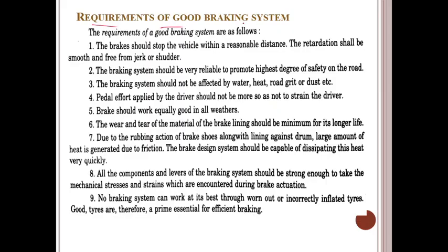So what are the requirements of a good braking system? Which are good brakes? The requirements of a good braking system are as follows. First point: the brake should stop the vehicle within a reasonable distance. The retardation shall be smooth and free from jerk or shudders. It means whenever we apply the brake on your vehicle, the vehicle should stop smoothly and free from jerk. This is the first requirement of a good braking system.